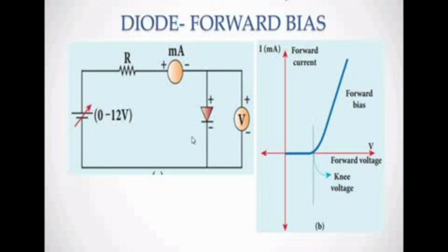It means a large number of charge carriers are passing through the depletion layer. In forward bias, the depletion region is very small, so by applying the external energy, the charge carriers pass through the PN junction diode. The flow of current increases enormously, so the graph shows it is like a conductor after a high potential difference is applied.